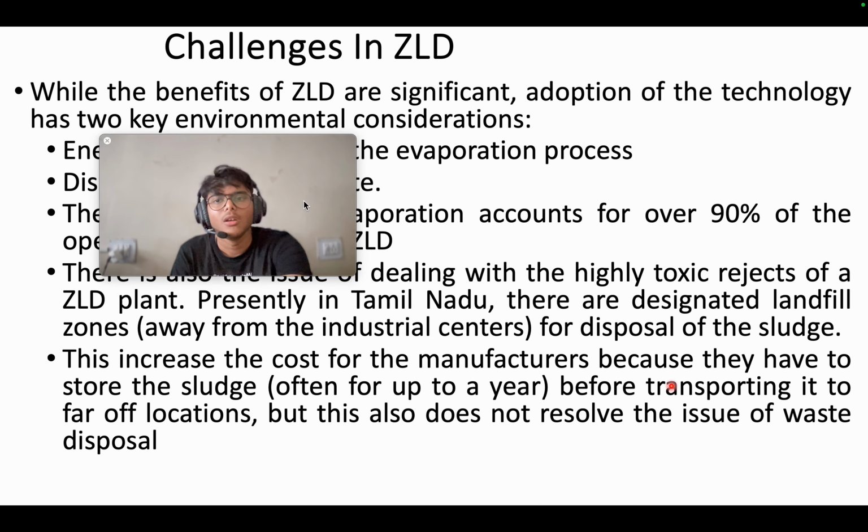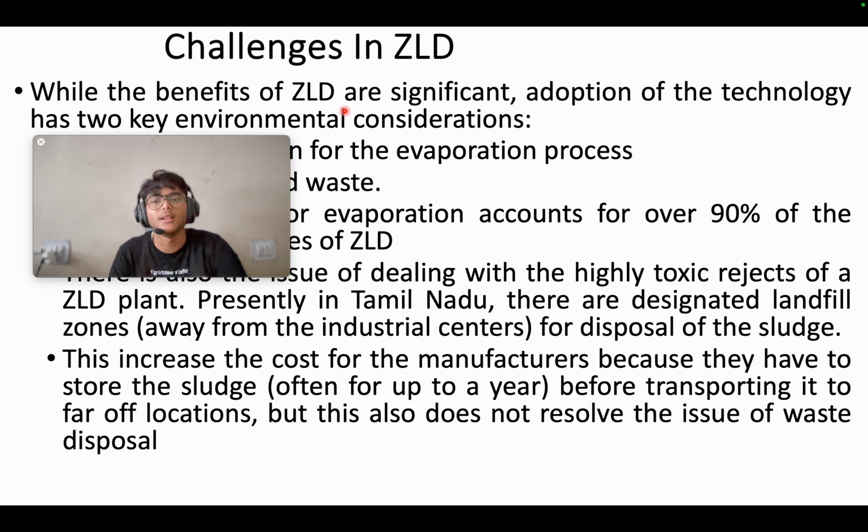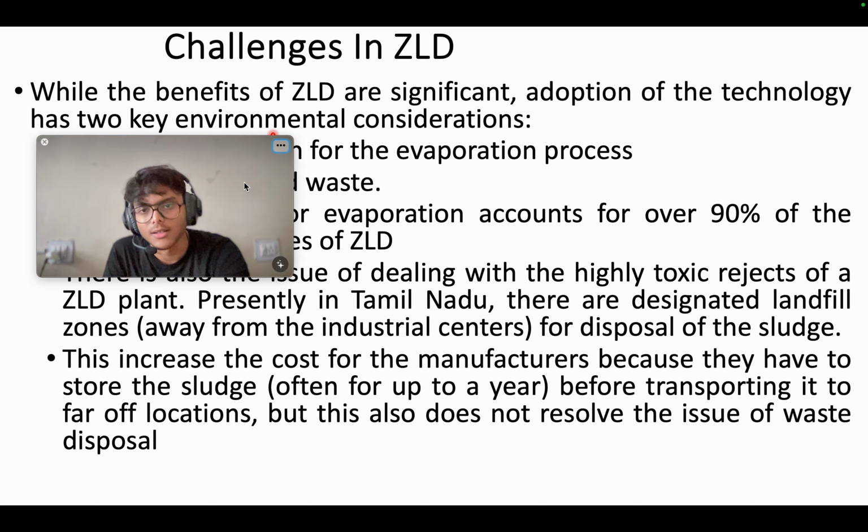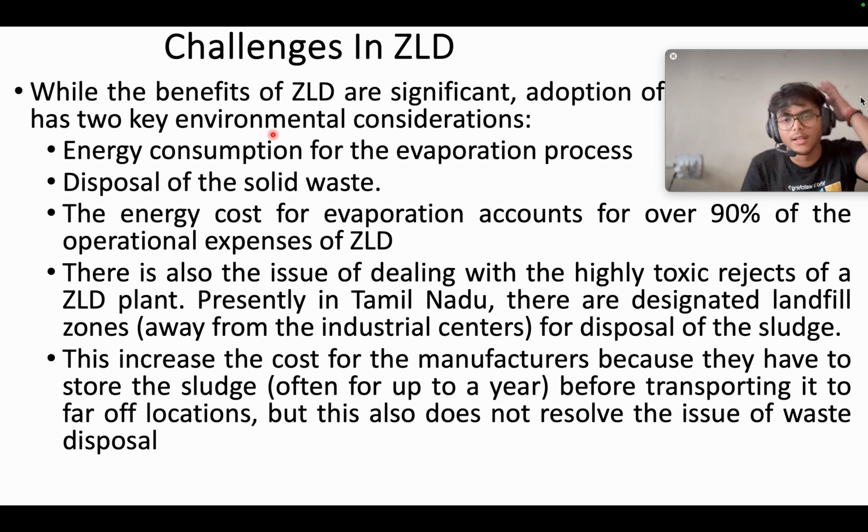Next, what are the challenges faced in ZLD? While the benefits of ZLD are significant, the adoption of the technology has two key environmental considerations, that is the energy consumption for the evaporation process and the disposal of the solid waste. The energy cost for evaporation accounts for over 90 percent of the operational expenses of ZLD. There is also the issue of dealing with the highly toxic rejects of a ZLD plant.